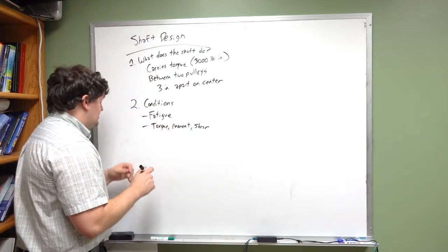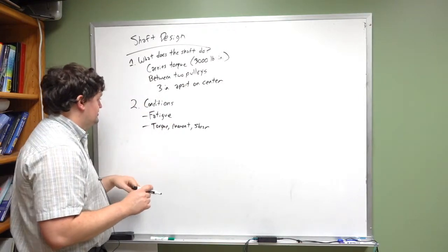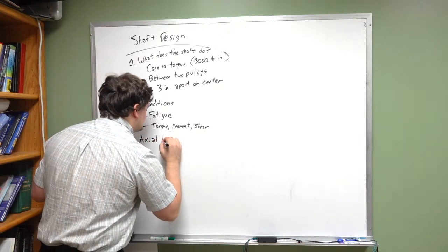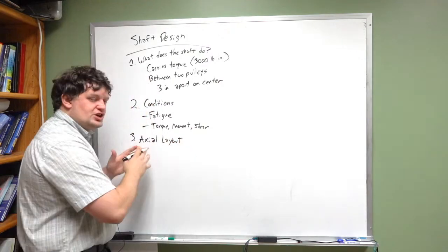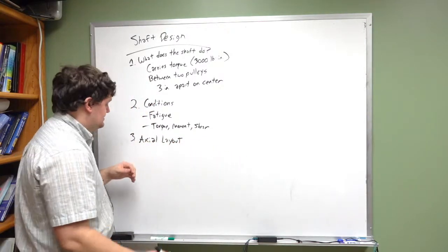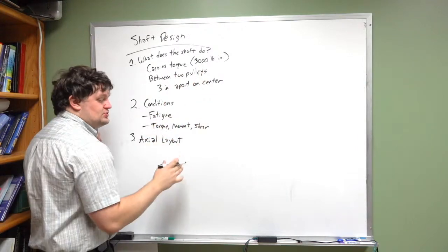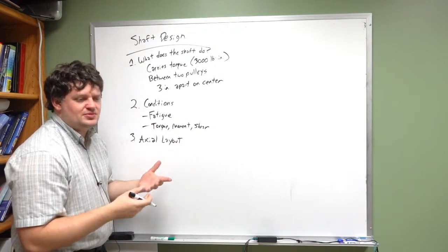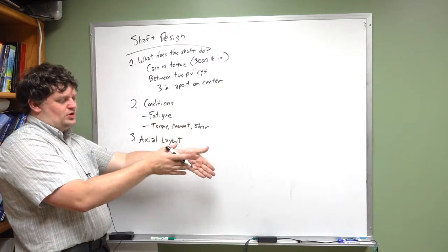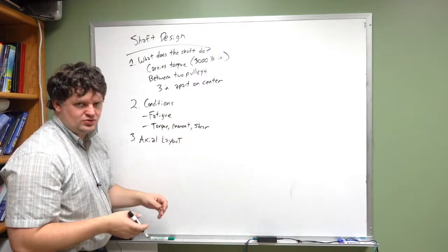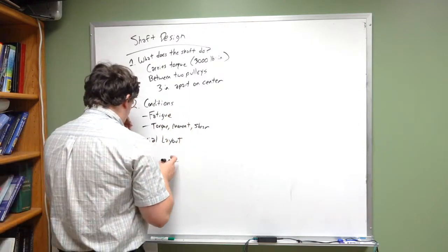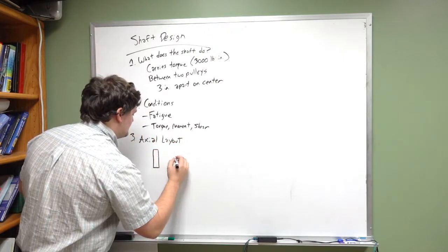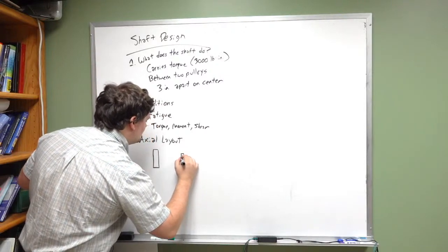So, what are we going to do for this design condition? Well, the next thing we need to do is our axial layout. How is our shaft going to look horizontally? We know we need to have these two pulleys be 3 inches apart, just as per the design conditions. This may be because of geometries of the machine. One belt has to face one way, the other belt has to face another way, that kind of thing. But in any case, we know that we've got one pulley here, and one pulley over here.